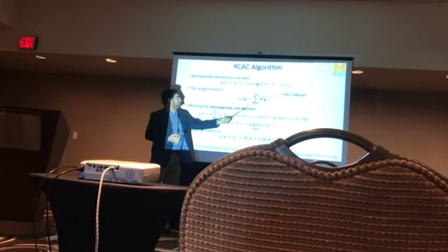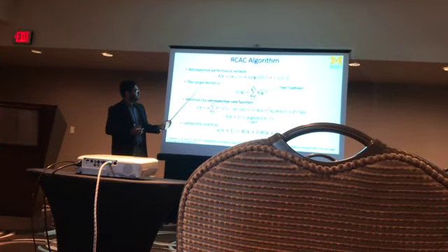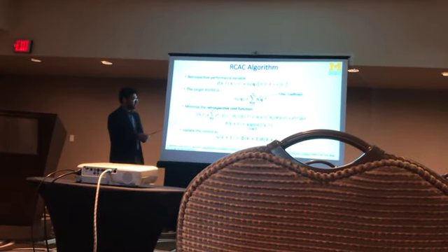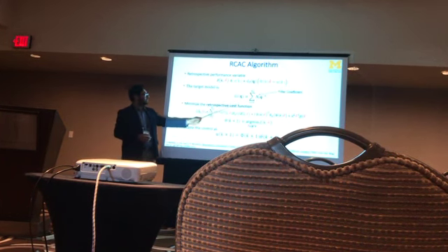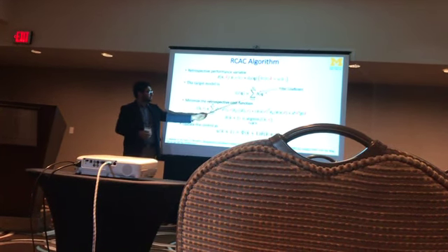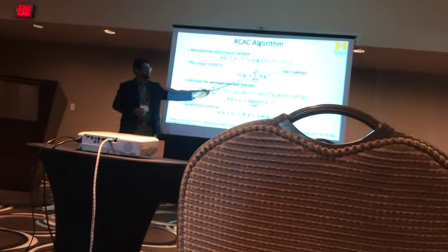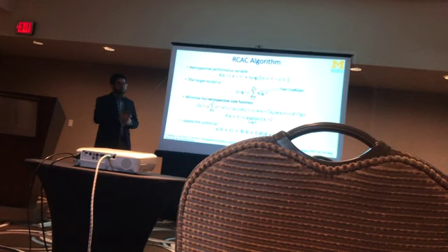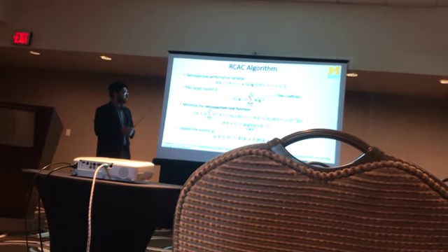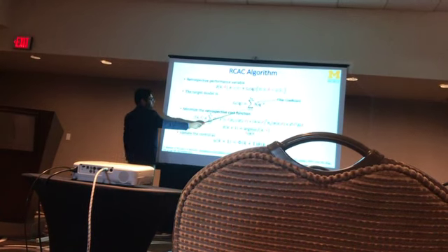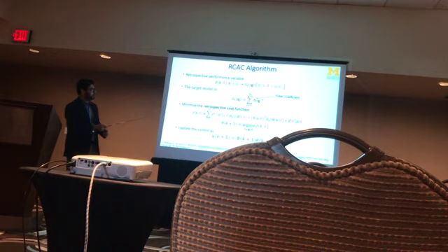This signal is passed through this filter, which is the target model, and the interpretation of the target model is actually very nicely shown in this paper. This filter is given by this FIR model. So we choose these coefficient matrices, and these coefficient matrices are the matrices which are going to define the subspace to which the input is going to be constrained. So this is just an FIR model with these coefficients Ni, and we define